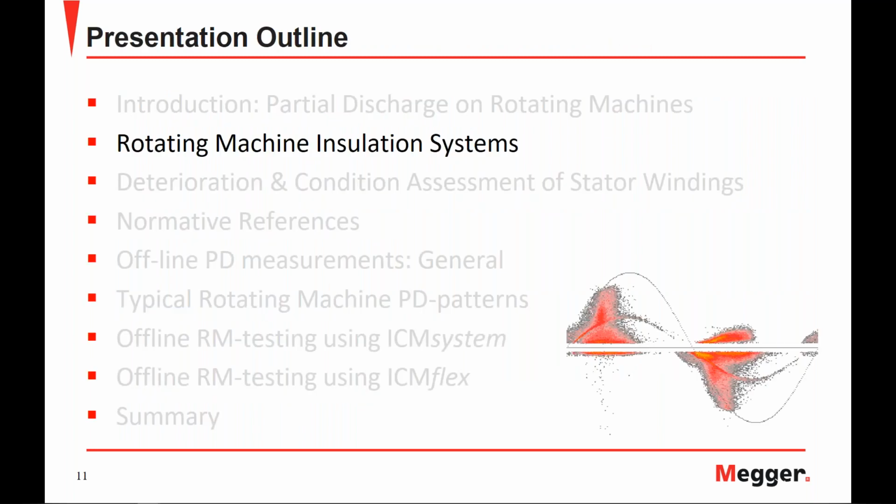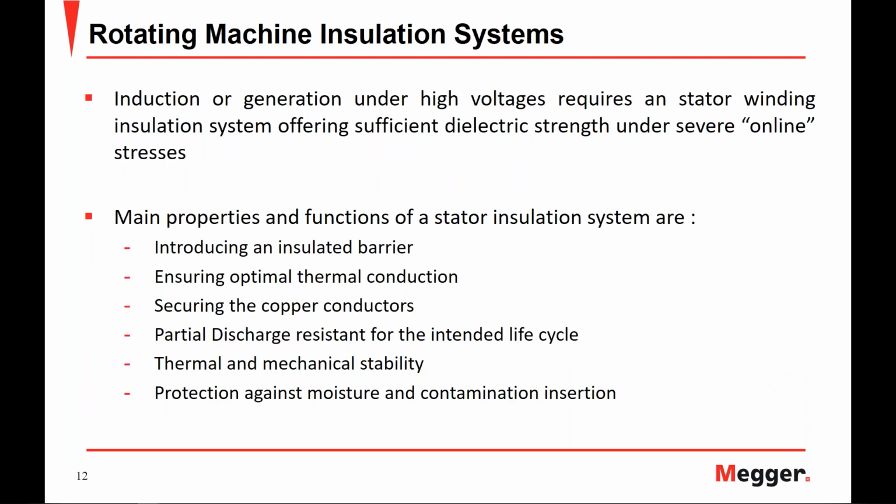Now that we've taken a look at an introduction to partial discharge on rotating machines, let's take a look at the rotating machine insulation system. The stator winding insulation system requires a certain level of dielectric strength, or withstand, in order to prevent insulation shorts during the online operation stresses,